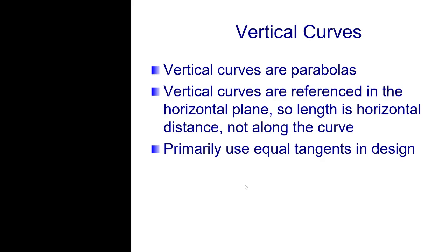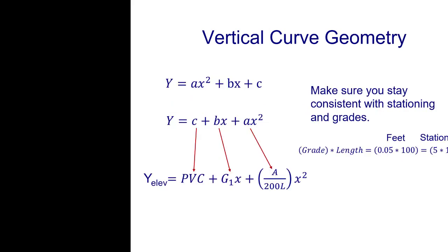Geometric design is the first thing that we're going to cover today. We're going to start with vertical curves. Vertical curves are parabolas. Vertical curves are referenced in the horizontal plane, so length is horizontal distance, not along the line. And the primary use is equal tangents in design.